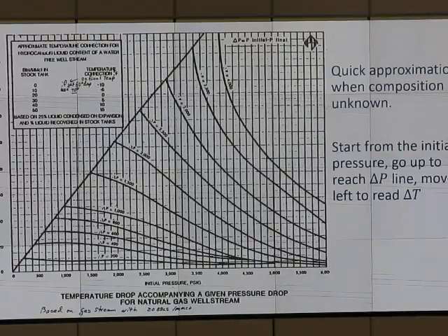And on the wellhead, you can choke at the wellhead. Right? It's closing the valve at the wellhead. So the wellhead can be used to choke it. So this means you don't need to have a line heater or anything if it is mainly liquid.